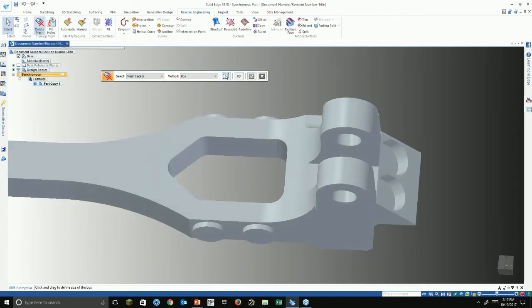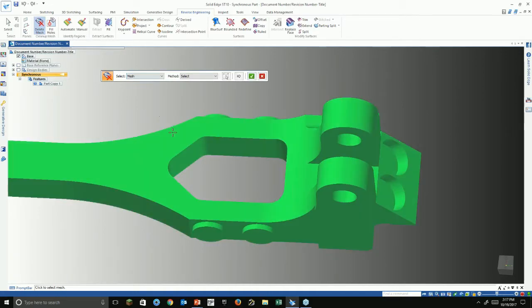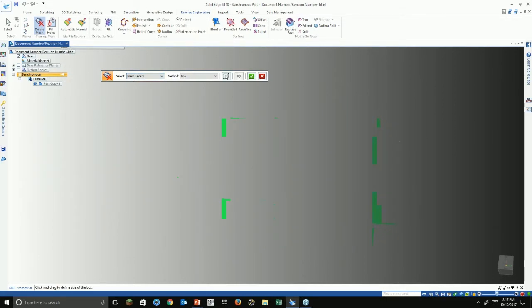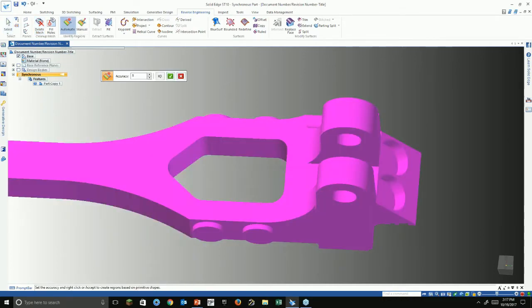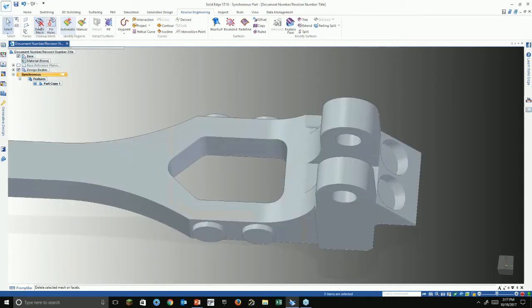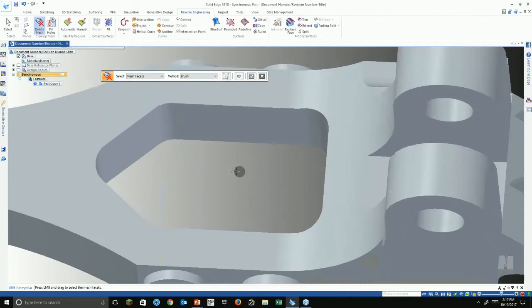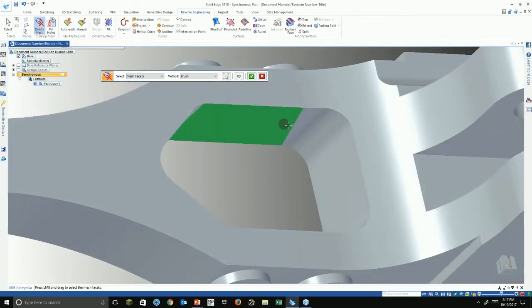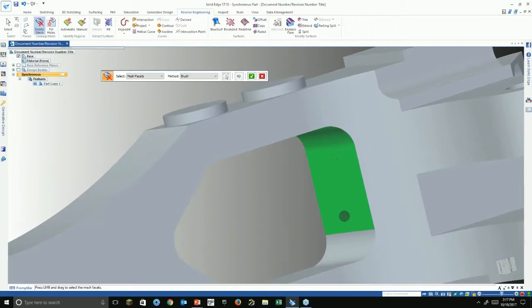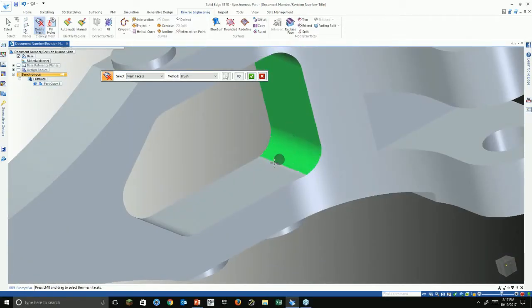So let's go ahead and get rid of some mesh. All right, so we have a couple options, mesh and mesh facets. Maybe for some reason you open an STL and it's got multiple bodies in there. Mesh would allow you to pick entire entities to get rid of, instead of just using what I'm going to do, which is mesh facets. So I'm going to say mesh facets. I don't want a box. I want to use the little brush selection. So I'm just going to sweep that brush and grab all these little triangles on the inside.